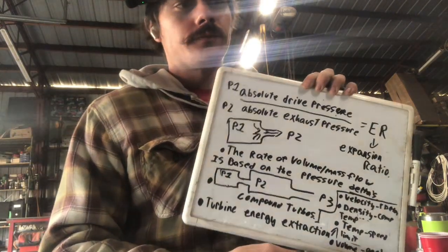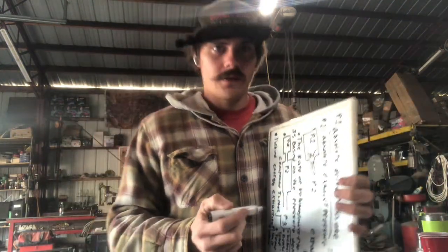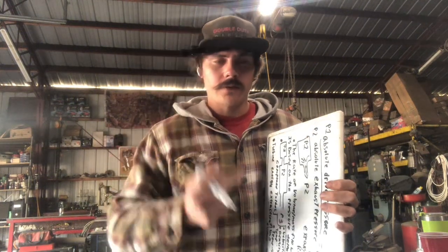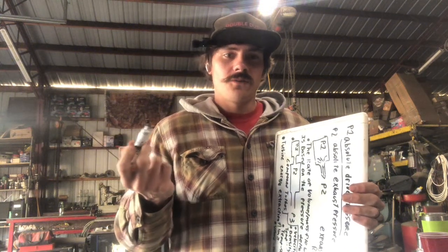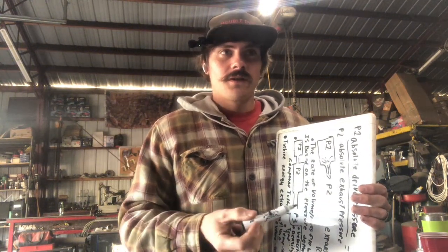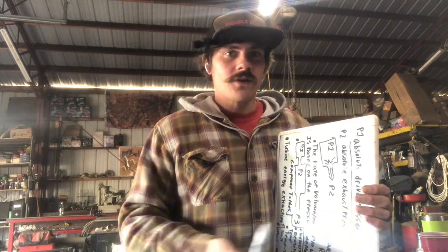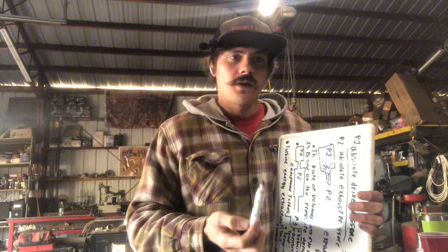Just a simple slide in the downpipe. Turn that out, so they can raise the exhaust pressure on the dyno. And what's pretty neat is that the power output does not change, because the expansion ratio is always way high, meaning with the free-flowing exhaust, the max gas velocity through the turbine wheel was already met way long ago, so it can't get any higher.